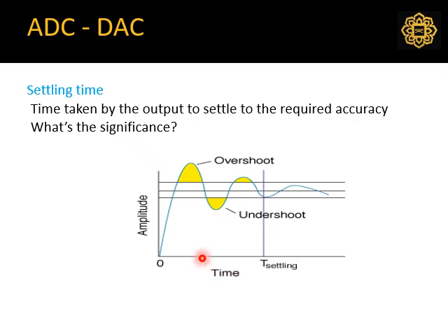Okay, settling time means in any system, when you have the input, the output changes, meaning to say your A to D conversion changes and goes up and down, and then eventually it settles into a nominal value. So this is any dynamic system. Op-amp is also a dynamic circuitry system, so it will have some time to settle down as well.